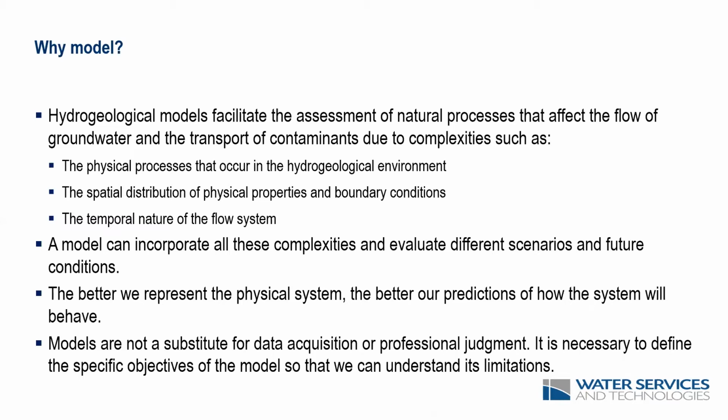So in a model, we can build in all these complexities and calibrate it to existing conditions or to recorded historic conditions, and then use that model to project future scenarios and assess what may happen in the future, depending on the problem that we are addressing. And of course, the better we represent the groundwater system, the better our predictions will be.